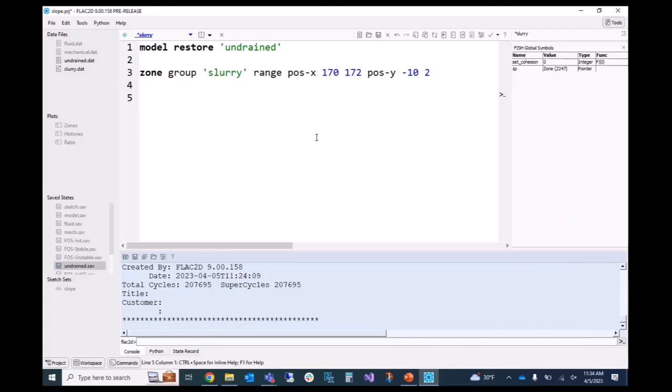The slurry wall cuts through all those things. So if I just clicked on that section between 170 and 172 and called it slurry, it's going to overwrite the names that I already assigned, the clay and the rock and the waste, which is going to mess up my material properties and everything else. What I really want to do is have that slurry group name in a different slot. And in the sketch, we do not yet have the ability to specify different slots for different groups. That's coming. For now, we don't have that. It always goes into that construction slot. You have no control over it. So I couldn't assign that slurry group because it's going to overwrite my geological names.